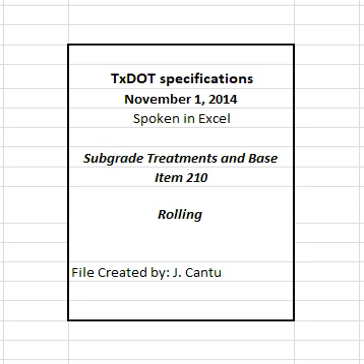Equip drums with tamping feet that project at least 7 inches from the drum surface, have an area of 7 to 21 square inches, are self-cleaning, exert a static load of at least 550 psi, and are spaced at 1 tamping foot per 0.65 to 0.70 square feet of drum area.